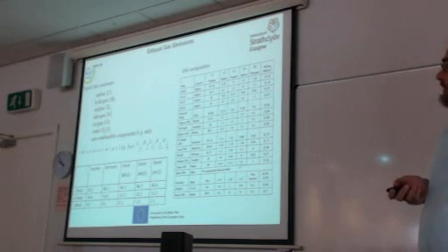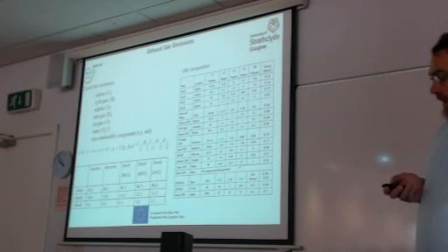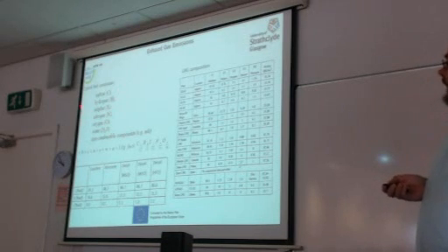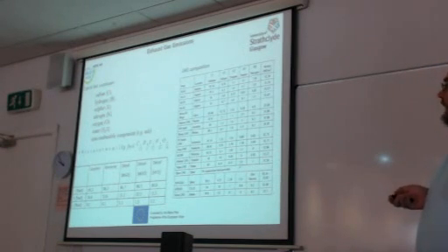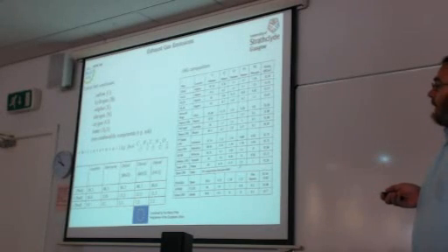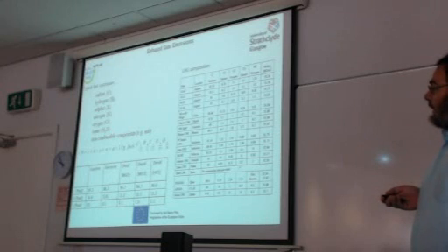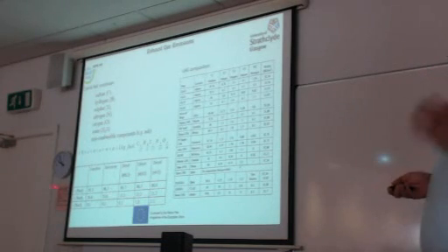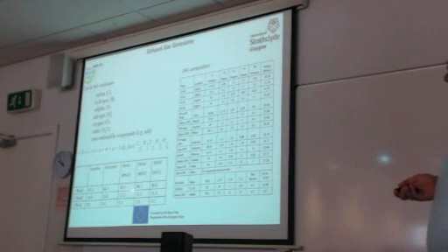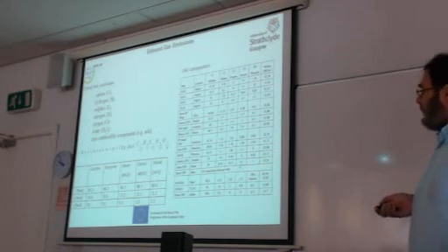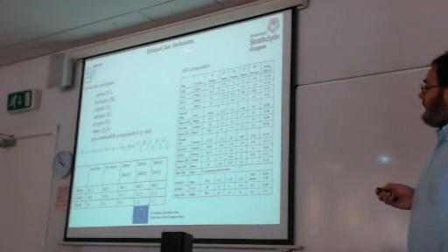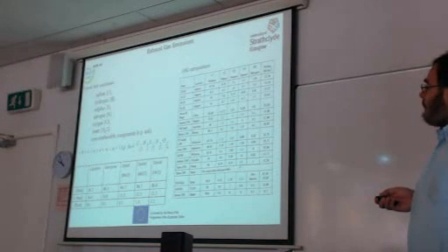Okay, so trying to explain why we have emissions in the exhaust gas and which kind of emissions will be expected, we need to see the composition of the fuel. And we know that hydrocarbon fuels basically involve carbon and hydrogen, but also other constituents like sulfur or nitrogen and oxygen or water and ash. And generally, in a diesel fuel, we expect 87% of carbon, 13% of hydrogen, 1% of sulfur. Of course, depending on the fuel, if it's low sulfur or normal fuel.